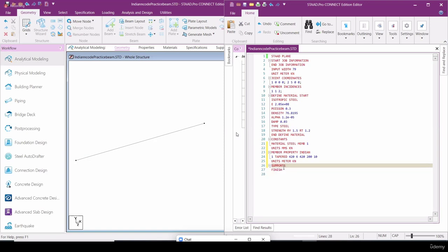And next we have to define supports. In this, what are the types of supports we considered for a simply supported beam in the previous class? One node is pinned and one node is roller. If I click Shift N, Shift N shows the node numbers here, okay. So 1 indicates the first node, 2 indicates the second node. So I am giving pinned to the first node, nothing but node number 1 space pinned. Clear? And node number 2, in a simply supported beam, that is roller.